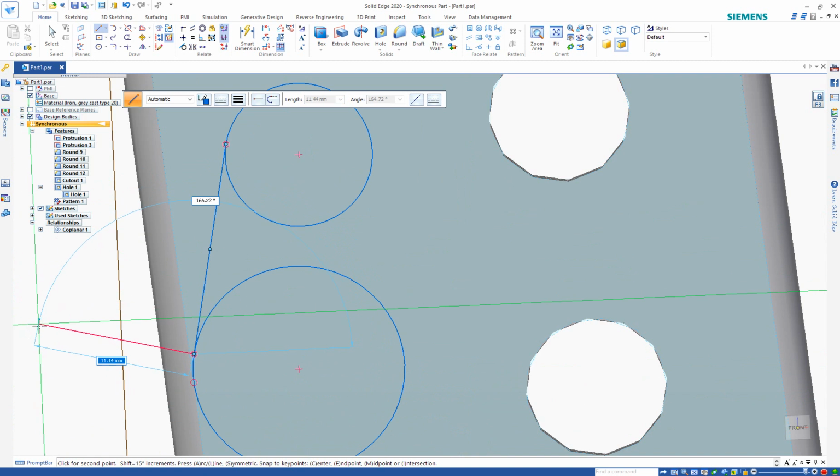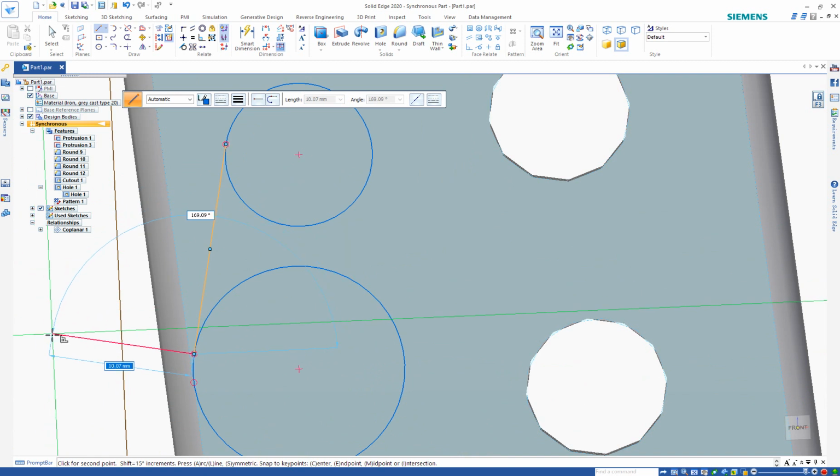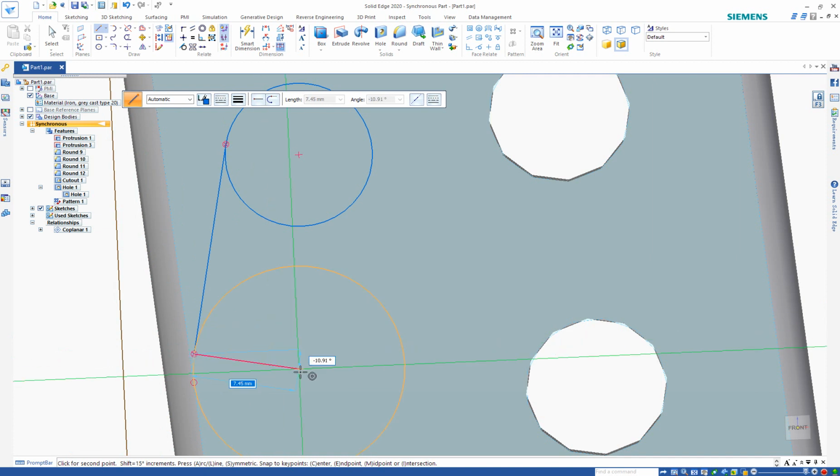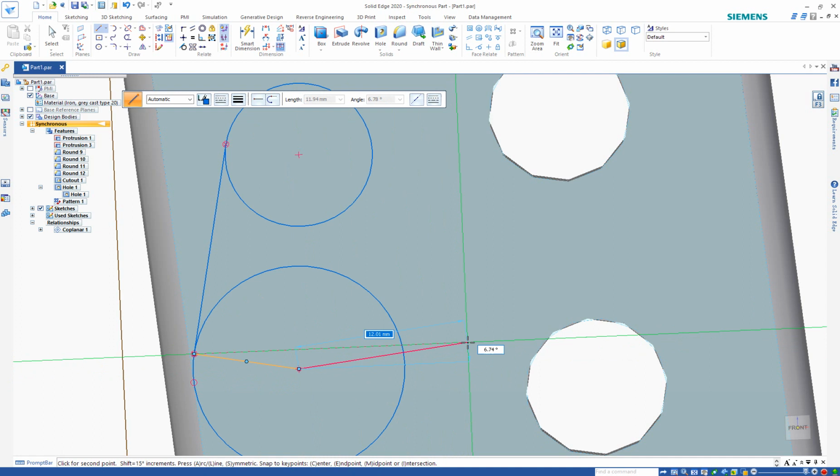For example, if you see this sign, here it means that the highlighted feature is actually perpendicular to the line you're drawing. And if you see something like this, it means the end of the line is snapped to the center of the highlighted curve.